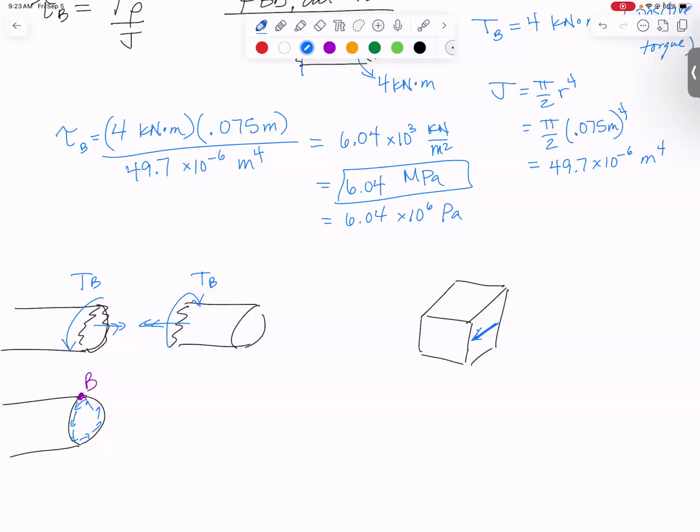That's the one you get from looking at the matching face on the diagram. So on the back face, you should have a stress in the opposite direction. That would not be in equilibrium. That would start rotating. So I have to also draw the induced stresses on the other two faces like that. And that's what the stress on the little cube would look like.